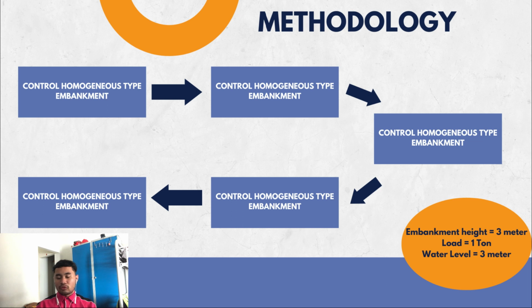Next, the thin core dam has been made using pervious soil for the embankment and 3 types of impervious soil as the core. For the next part, we design the zone dam. For the zone dam, pervious soil has been used as the material for the embankment, while 2 types of semi-pervious stabilized soil are used for the outer core, and pervious soil will be used in the inner core.